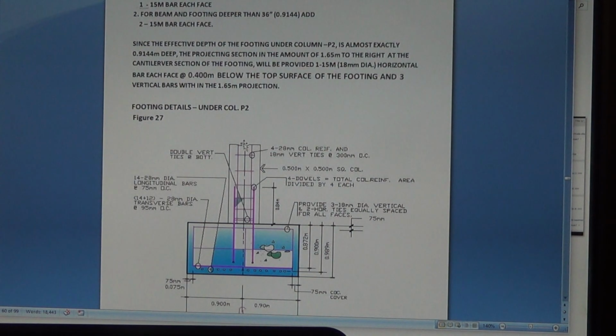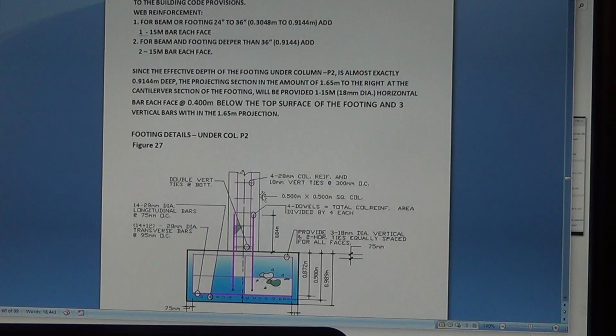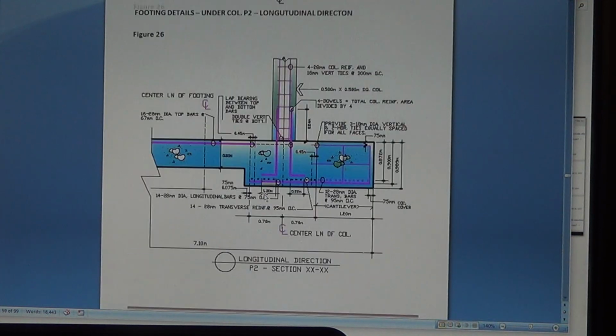What else are you going to see here? Yeah. So this is the transverse direction. When you cut in the transverse direction, the longitudinal bar here is in cross section, and here's the transverse bar, lengthwise. Again, how long this bar is and how you cut it also has a theory and calculation for that. What else? Okay, here's the larger column. The interior column is larger than the exterior column.